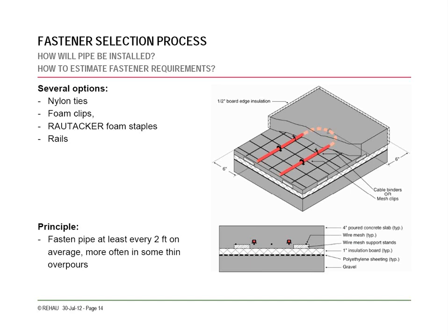If you're using nylon ties or clips or whatnot, we estimate these at every 2 feet. You can usually spread them out a little more towards 3 feet, but then you're going to need extras on the end. So if you do every 2 feet, you're basically just dividing your linear pipe length by 2. It's the quick and easy, dirty way to calculate it.